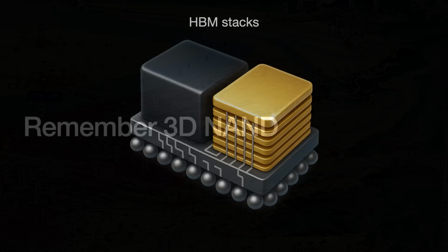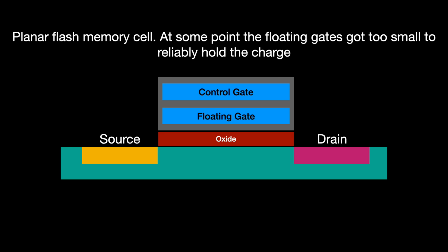The NAND industry once faced the same physical scaling issues with planar. After several generations, flash memory cells got so small that 1. they were too difficult to manufacture, and 2. their floating gates held so few electrons as to cause variability errors. With 3D NAND, manufacturers step back to a larger, more reliable flash memory cell, but more than compensate for that loss in bit density with huge vertical stacks.